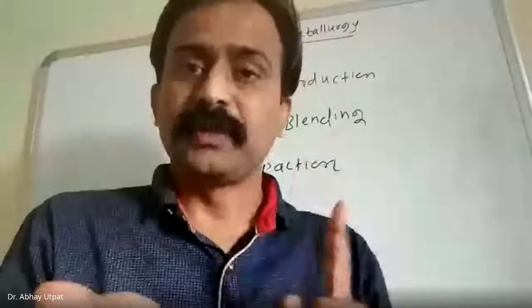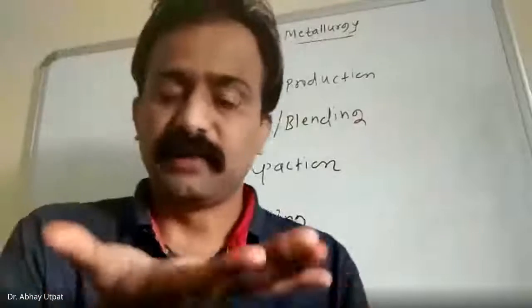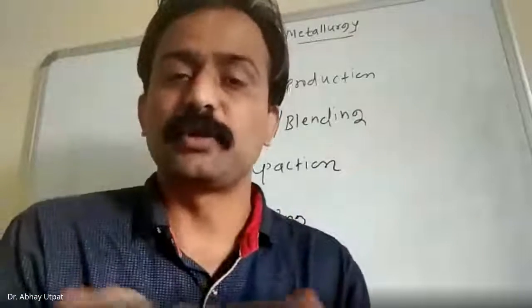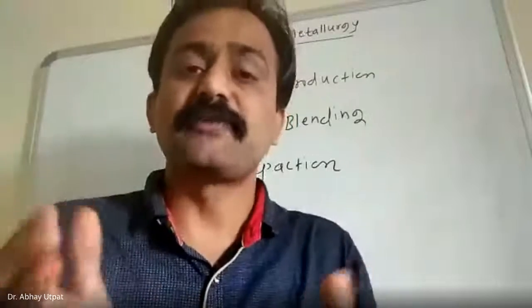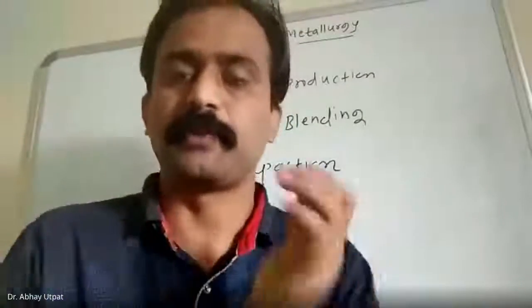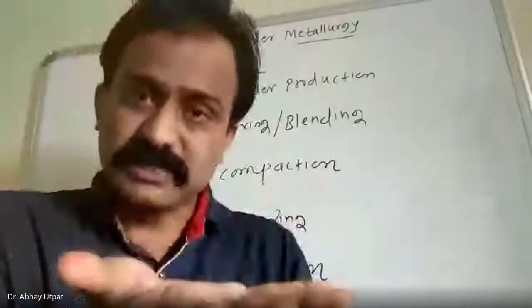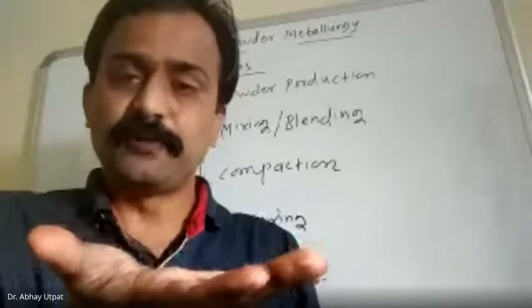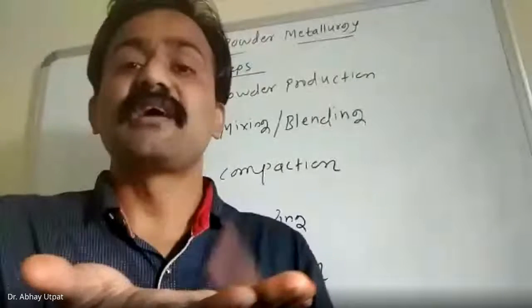So you have to give strength to that component. That component is called as green component. You have studied green molds. Green means raw, which is having less strength, not power, sorry, I will take my word back, which is having less strength, which is fragile. So that fragile component, if you are going to give strength to it, it must be fired.